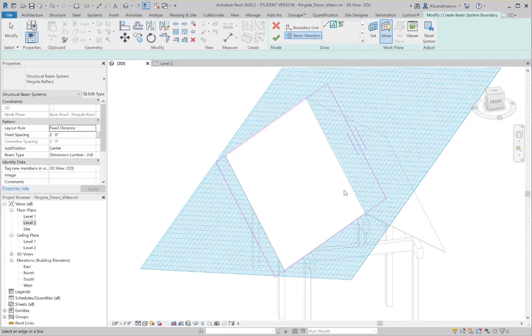So if you had to build up, say, a trellis or a lattice work where you needed multiple layers of framing members that were spaced or run perpendicularly to one another, you could effectively build up a trellis like this and then simply set the reference work plane on top or the bottom of each layer of that trellis as you were building upwards. I want to change the direction to here, so I'm going to click that.